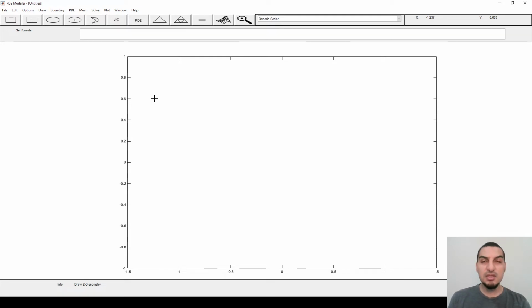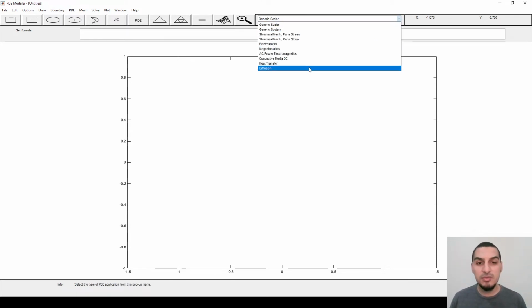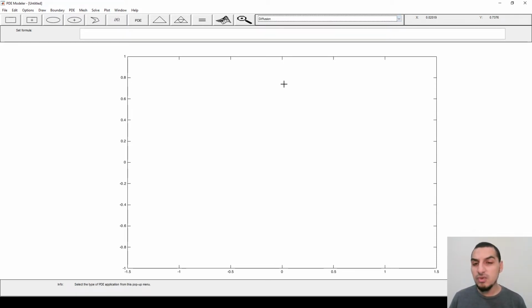And this is something that we have to understand, that even if I choose the problem that I'm solving, a diffusion problem, the software does not understand the diffusion coefficient, does not understand concentration. The software deals with the inputs as pure numbers. For instance, if you define the partial differential equation with a negative diffusion coefficient, the software will have no problem solving the problem with an unrealistic value of the diffusion coefficient. This interface is just a translation, an easy way for you to put in your inputs, and the software will translate your inputs into equations.